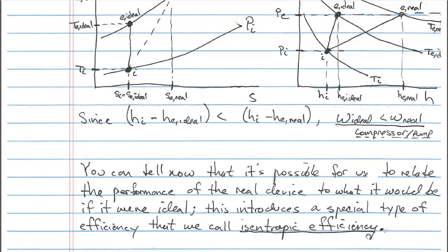Should we call this isentropic efficiency, or should it be called isentropic coefficient of performance, or isentropic effectiveness, or what's a better term for it than efficiency? And the reason why we have these debates is because it doesn't fit that classic definition of efficiency of what you get divided by what you pay for. Regardless, that's what it's called.